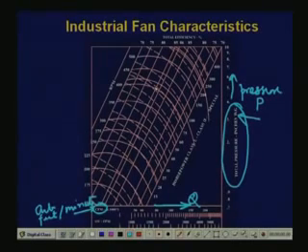You see part of the fan characteristic is shown, and a family of curves. So what are these curves? They are the various operating points. For example, this line starts with the number 500, and here it is written RPM. So if the fan is made to rotate at 500 RPM, then the pressure-flow characteristic follows this curve. Similarly, you have a family of curves for various speeds.